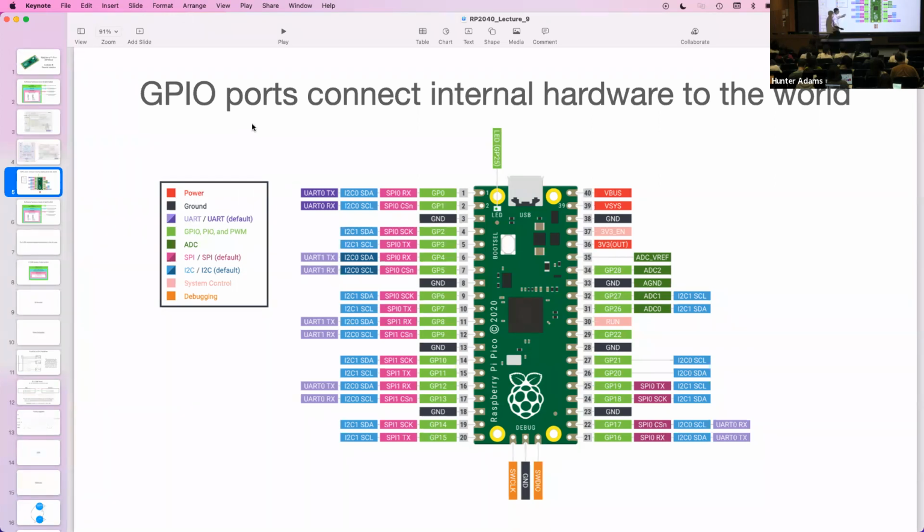It may also be something as simple as you would like for all of your wires to come out of one side of the board for mechanical reasons. Maybe you're building some sort of a robot where it really helps with the design of the robot to have all of your electronics coming into one side. And sometimes that might be possible with strategic choice of which GPIOs you map signals to.